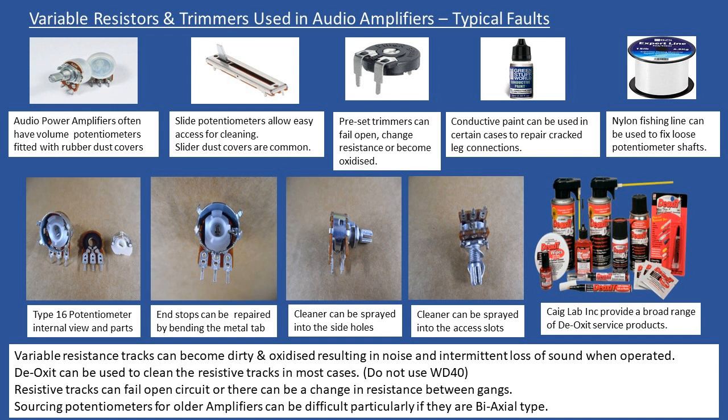So if you maybe have a balance control, treble or bass, the shafts of these potentiometers are quite short. If you're cleaning them, originally you would have lubricating grease around the potentiometer shaft.